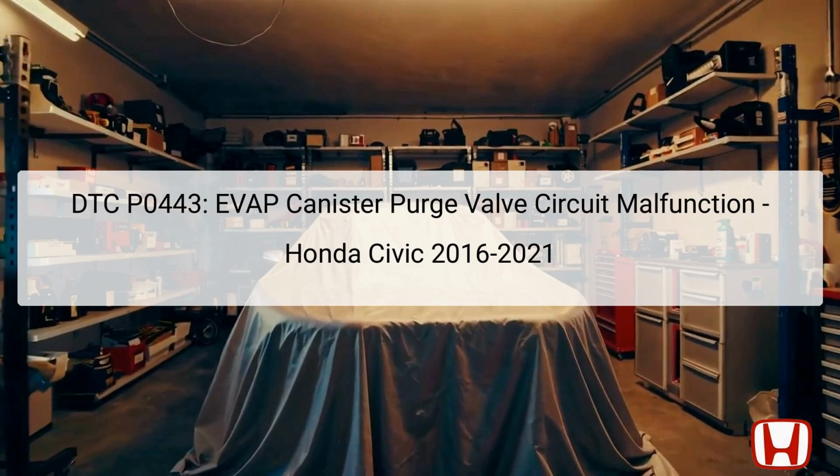The EVAP, Evaporative Emission Control, system is essential for capturing and reusing fuel vapors that naturally occur in the fuel system, thus preventing them from escaping into the atmosphere. The EVAP Canister Purge valve is typically located in the engine compartment and has connections to both the canister and the engine's intake system.